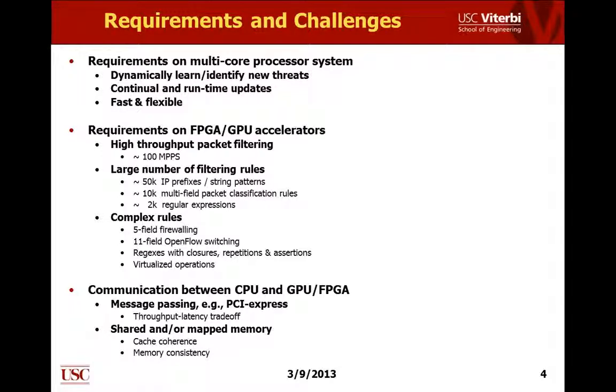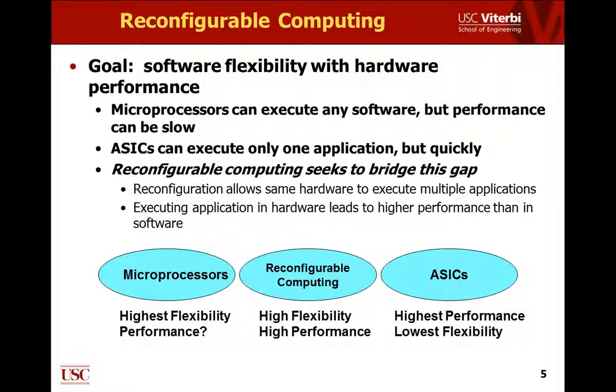So what it means is that sometimes we will not be able to store these patterns completely on the FPGA device. We may be exceeding the available block RAM or the available static memory in this system. So we will be forced to use external memory, which will add a large penalty for the performance due to the access latencies you have in those systems. So this work is exploiting